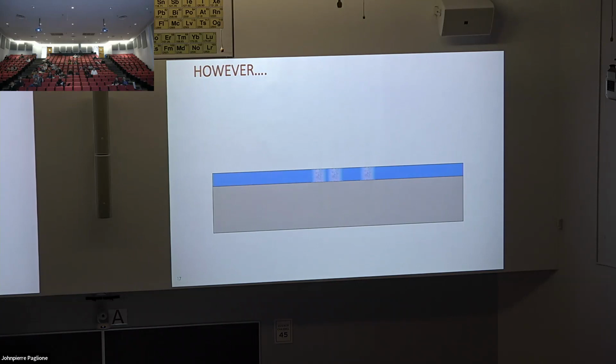And this is an intrinsic limit of e-beam lithography. So then suddenly you have something that is quite wide, you try to go and develop it. And as you try to move features close to each other, they start to merge together. So this is why we have this approximately 30 nanometer intrinsic limit with conventional e-beam lithography. Yeah, so this is what it is. Secondary electrons are your biggest enemy in polymer-based e-beam lithography.